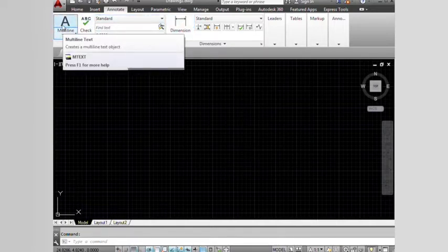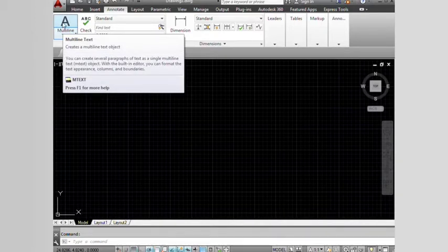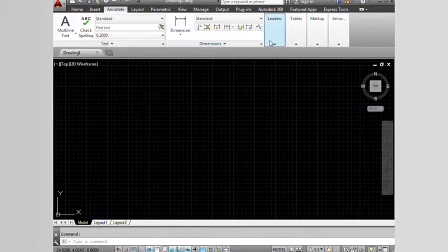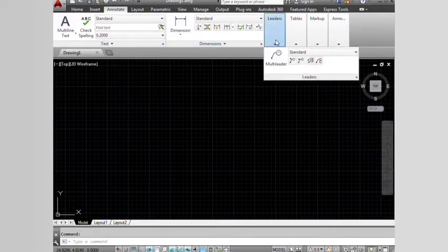So text descriptors, so information that we just want to type in as regular language in regular sentences to provide some additional information for the user of our drawings. We also have annotations that have a leader on them, in other words, an arrow pointing from the text to the specific location on the object for which we want to provide additional detailed information.